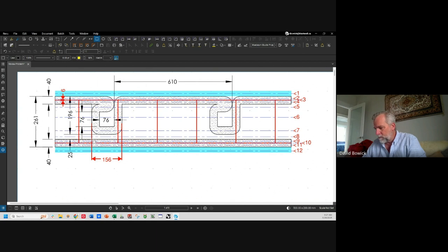The 3D printed wall assembly consists of a structural layer, which is the upper layer, and a non-structural veneer layer. This is an exterior wall condition, which is the lower one, tied together and cavity filled with insulation. So here is the cavity fill insulation that I'm just highlighting in yellow. What we're going to do is calculate the effective R value of this assembly with all of the insulation in it.